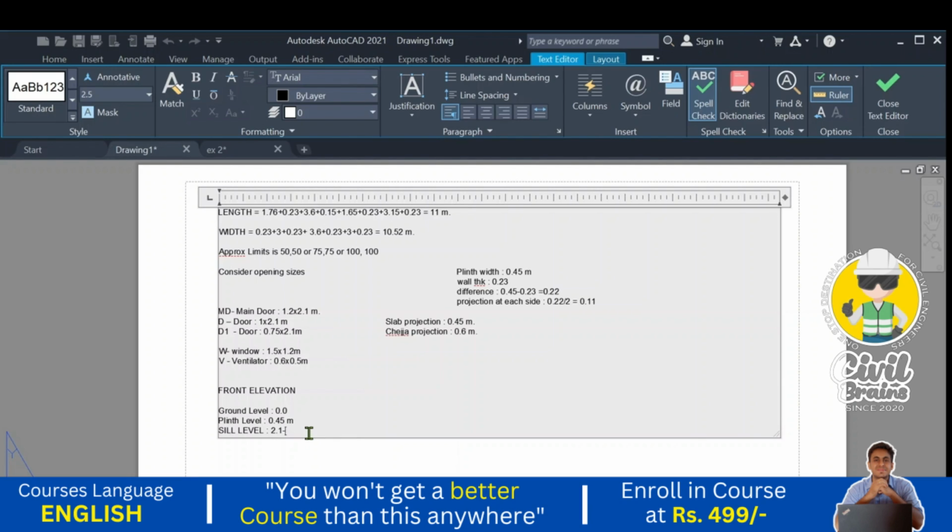Total height of the lintel. From the bottom of the lintel we need to calculate. From the floor level to the bottom of the lintel, that is 2.1 meter. That is already given in the question. From the floor level to the bottom of the window, that is 2.1 meter, and we are considering 2.1 meter minus 1.2 meter is equal to 2.1 minus 1.2, so that is 0.9 meter. 0.9 is our sill level.